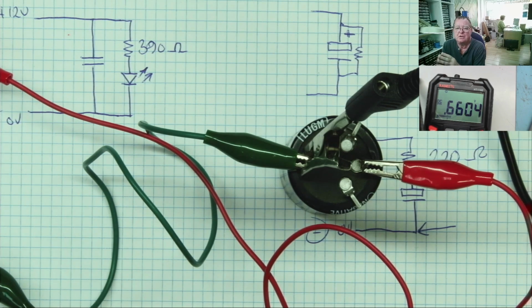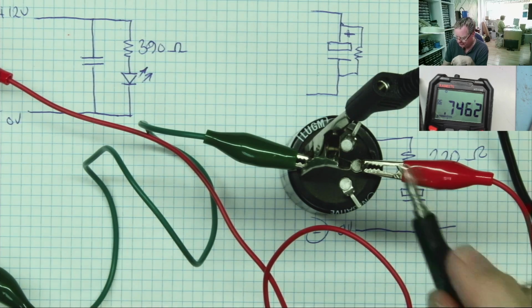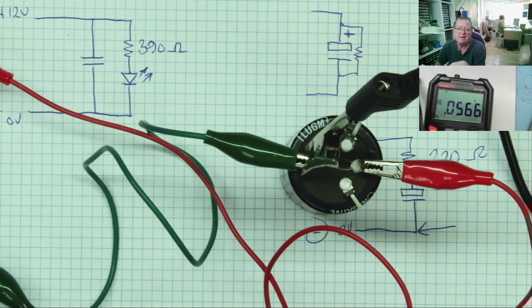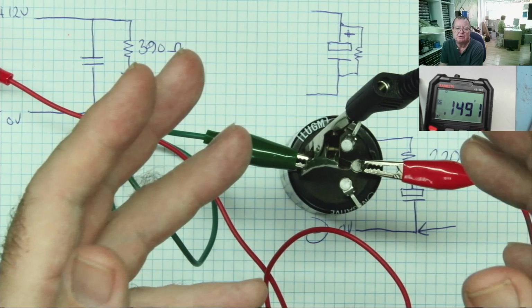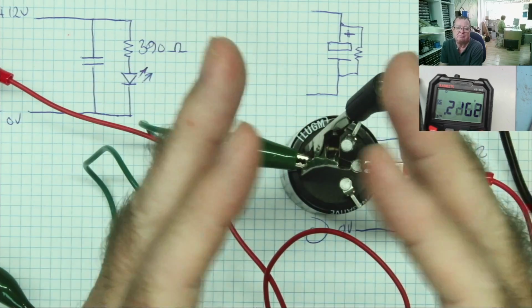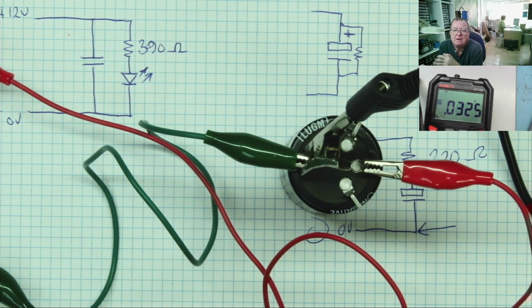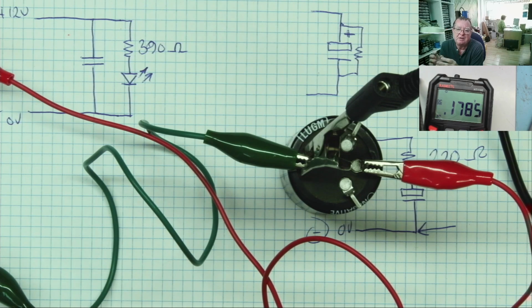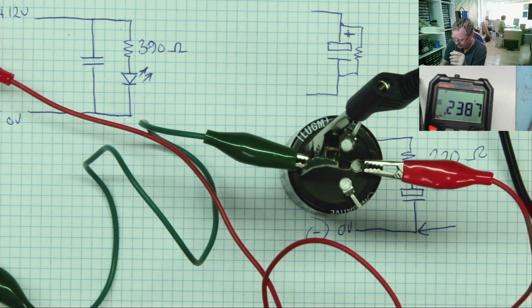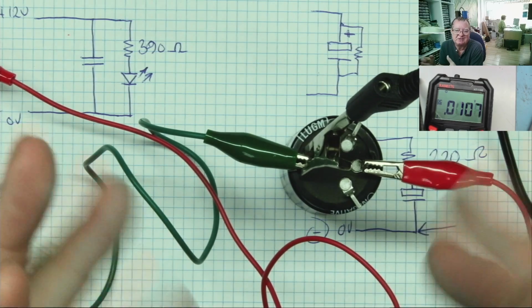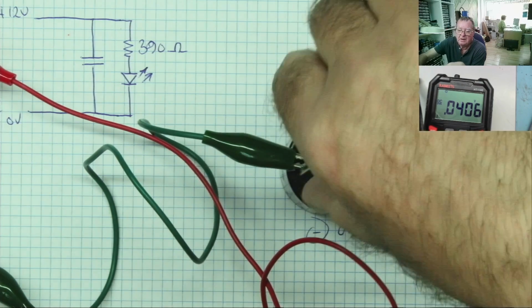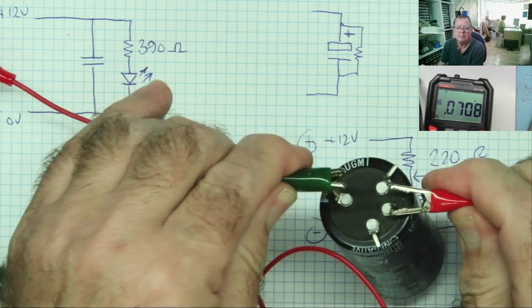In fact, so fast that normally you would have parts of the circuit connected in such a way to prevent that from happening. It's not very good for the capacitor to charge and discharge that fast, because as you do it, A, you put an extremely high strain on the dielectric inside the capacitor, and B, it's not particularly useful. But there are some circuits, trigger type circuits for high voltage flashlights. I don't mean flashlights like a torch, I mean like the stroboscopic lights, where you want to discharge a capacitor extremely rapidly into a xenon tube to get a very short duration flash, photographic flash, that sort of thing. So there are circuits where you will want to do that sort of thing, but you will generally have special capacitors in those circuits to make sure that they can do it. So that's how fast we can discharge a capacitor: immediately, pretty much.